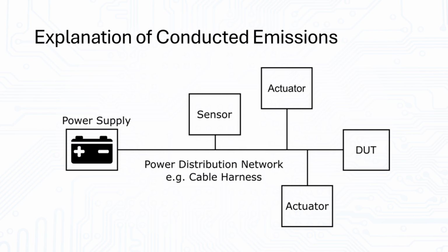As the name suggests, the term conducted emission relates to unwanted transient signals that propagate via conductive materials. These emissions are caused by electronic-based systems, such as the block labeled as DUT, which stands for Device Under Test, and are propagated through the interfaces into the connected networks or systems. One of the most critical paths that these conducted emissions can take is into the power distribution network. Such a power distribution network usually connects a multitude of electronic systems via long cables.